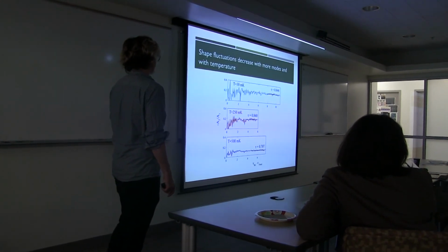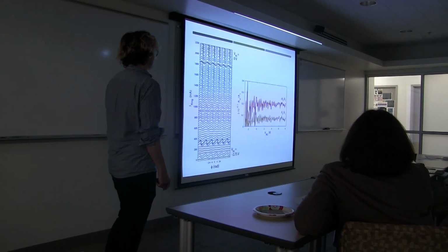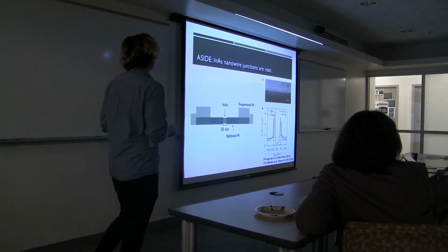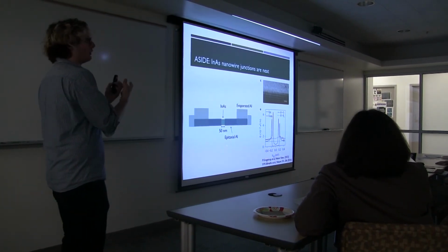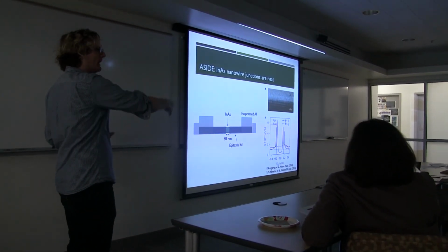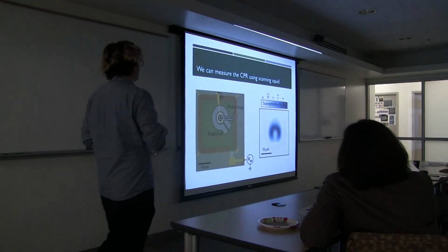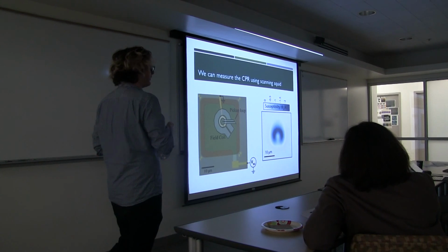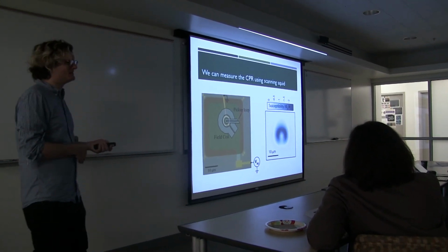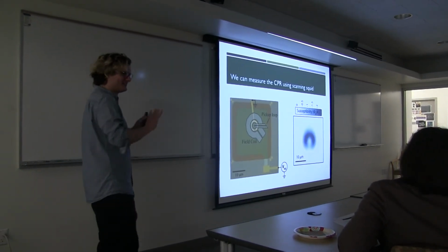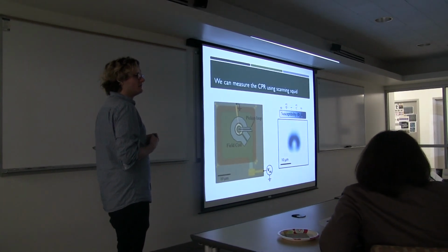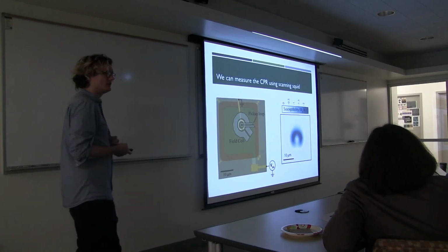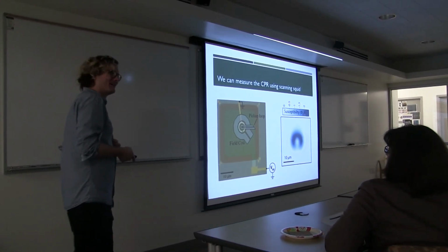I'm not sure how they were made. You were talking about epitaxial growth. These nanowires grow with the epitaxial aluminum on them, and then we evaporate an aluminum ring on top of it. The evaporated aluminum is a couple hundred nanometers, I'm assuming. And the epitaxially grown layer is thinner, tens of nanometers. So that's information I need to get out of my collaborators.